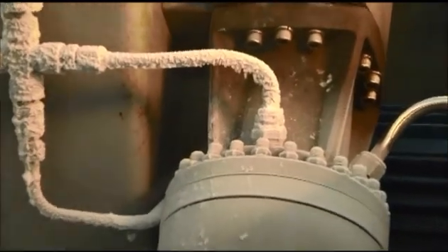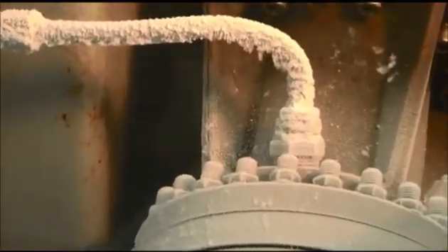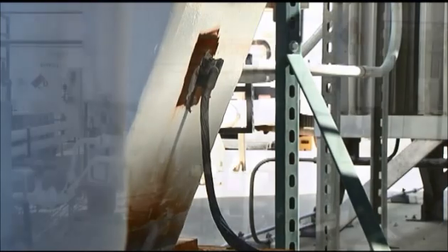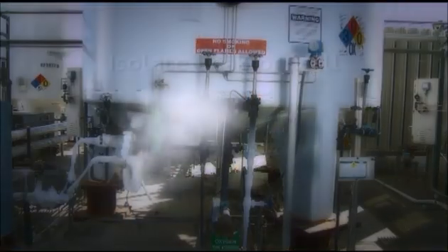In addition, all oxygen piping systems and related equipment must be electrically grounded. Engineering controls such as these are very important to prevent oxygen leaks and fires. If there is a leak or spill, it's important to isolate the leak or spill area and evacuate personnel from the area. Contact the appropriate fire and emergency response personnel or notify the emergency team at Praxair. Don't try and do it yourself unless you've been trained and are qualified to do so.